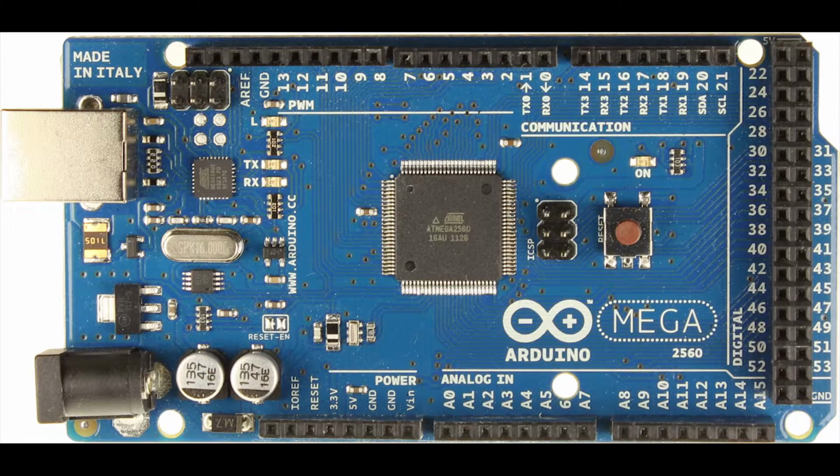The Arduino has many different connection points for attaching various circuit components. It can also supply 5 volts of power to a connected circuit. Today, we will be using the digital pins, which are labeled 0 through 13, the power pin, labeled 5V, and the ground pin, labeled GND. Other pins will be used in other labs.